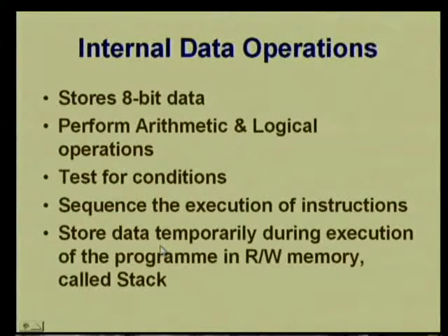Then lastly, it can store data temporarily during execution of the program in read-write memory called the stack. So while it is executing a program, suppose the available internal registers are exhausted, then it may need some more data for processing. In such a case, some of the data can be stored temporarily in a part of read-write memory which is predefined by the programmer as a stack.